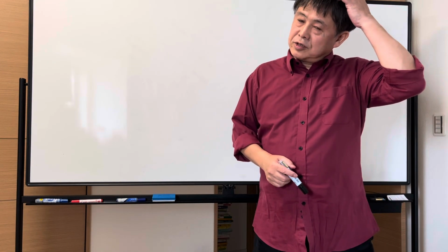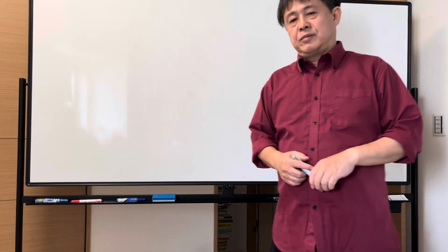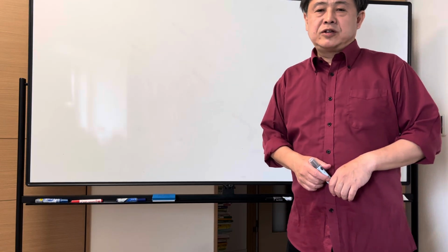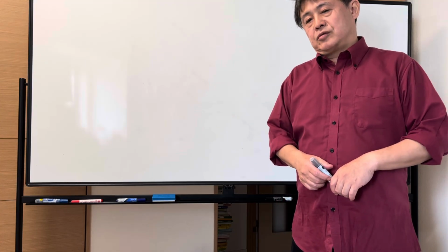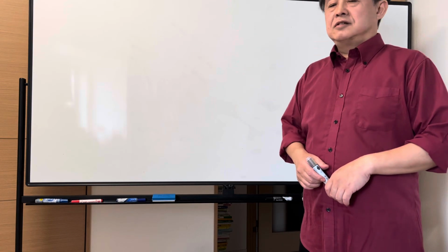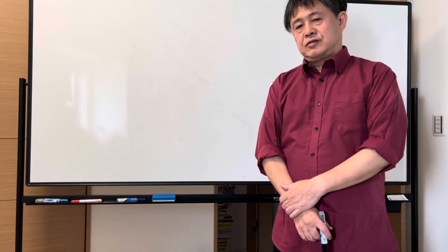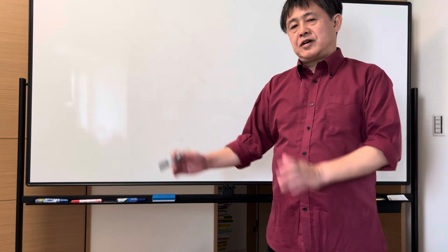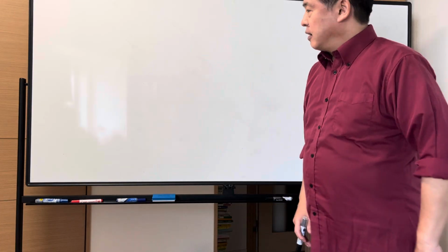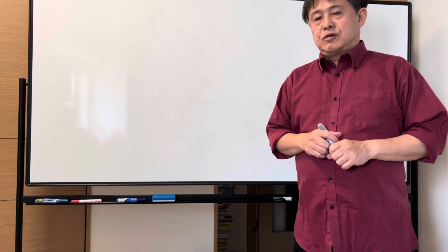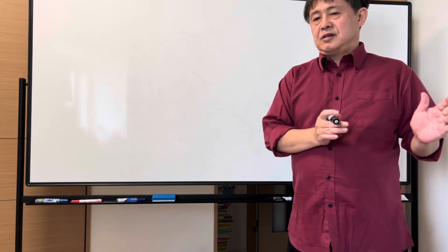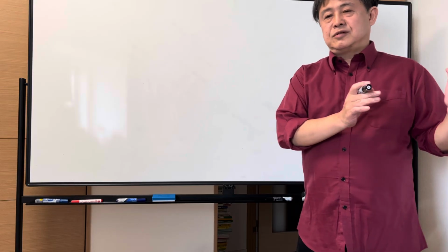In this recording, I'd like to explain how the input noise is affected by output noise. In the case of an LDO, the input is a voltage difference and the output is a controlled, linear regulated output voltage. In the case of a PLL, likewise, the input clock frequency is used as a reference to make a higher frequency, from 30 megahertz or 40 megahertz to 300 megahertz or sometimes gigahertz. The input clock frequency's phase noise affects the output phase noise.